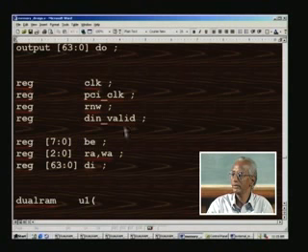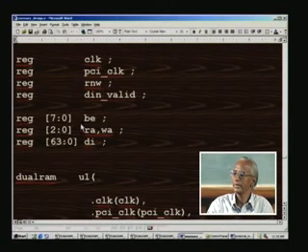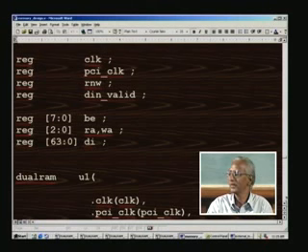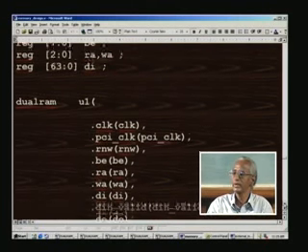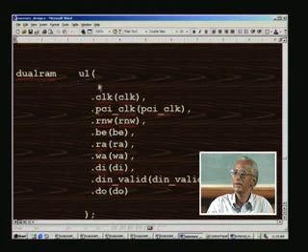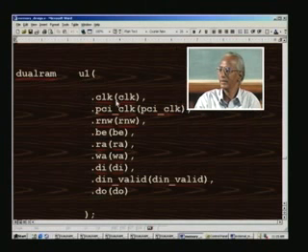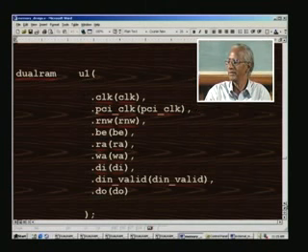So you need to declare it as, sorry, these are all inputs still. B, there are inputs to this design, right. So all of them are inputs. So you need to declare them as reg, and only one output is D naught, that has been declared there, and then we invoke the actual design and instantiate it here, and only one instantiation is used, and these are all the listing of the IOs that we have already seen.